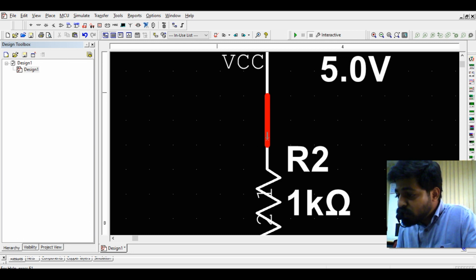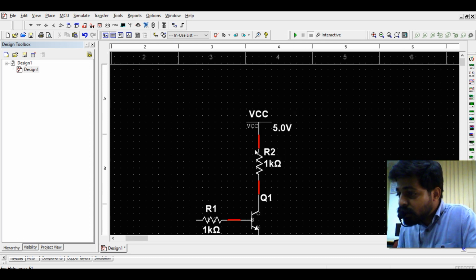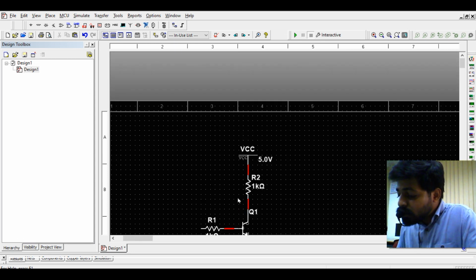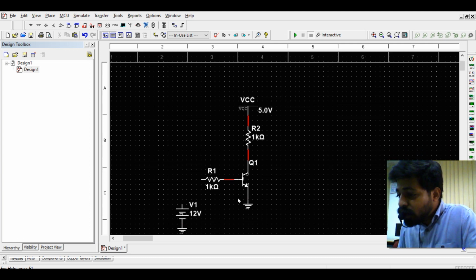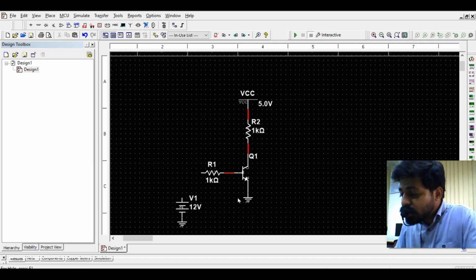I have the option of zoom in and zoom out also, by using the scroll wheel on the mouse. I can use the up and down arrows also so that the sheet of the circuit workspace will move up and down. So here I will use one click at one end, and go with another click at the other end so that the wiring will be provided between these two. Where I need to keep my ground downwards, I just click on my ground so that it is selected. Then I use the down arrow. The component also will move.